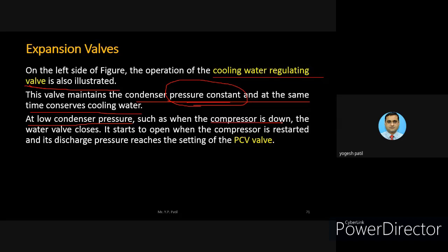Then what happens? As there is no requirement of cooling water from the cooling tower, the water valve closes. So obviously, what action is required? That water from the cooling tower is required to close. Otherwise, what happens? There is no compressor running and we are passing the water into the condenser. There is no meaning to that operation. That valve will open when the compressor is restarted. Okay, the compressor is down, then the valve is closed.